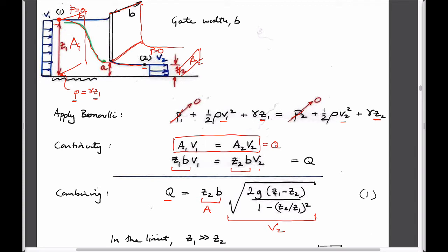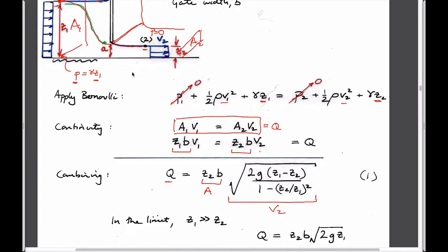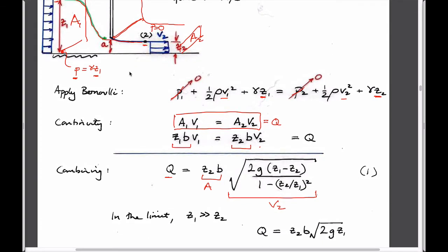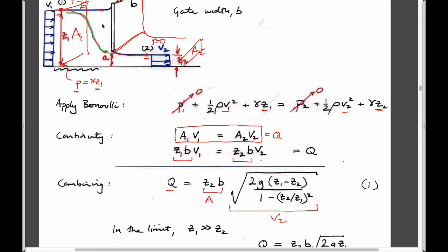Upstream height of the system above here, and downstream height. Typically the assumption is that when this comes out, it's also roughly the same as this separation. Typically it's slightly less than it. It'll say at the bottom maybe 0.6 times this, just by so-called vena contracta effects, that this actually does taper down. But if you measure the height here, then you can figure out everything you need to know in this system.